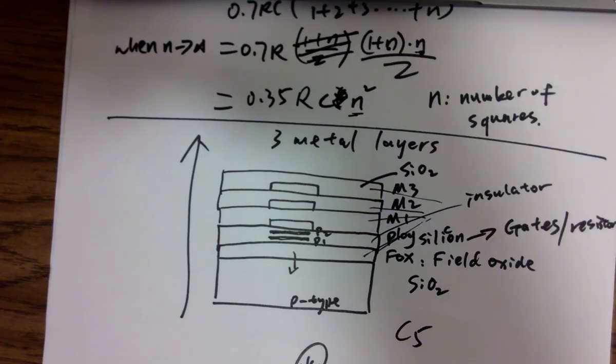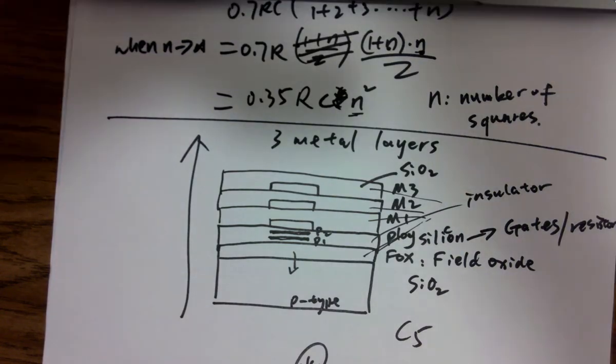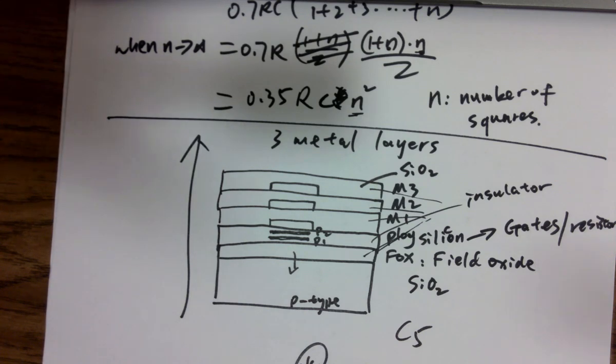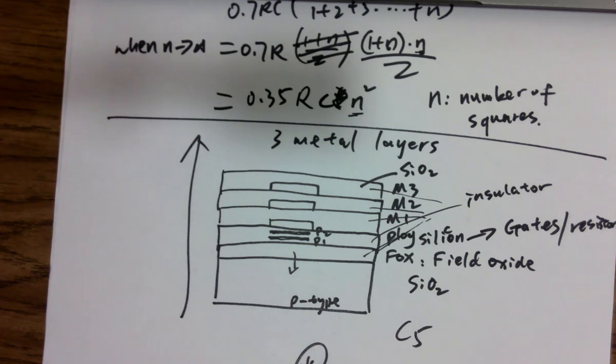and then come up. So you can imagine if you have like 40 layers of the PCB, you can highly integrate all the components in a smaller area. That's the motherboard of the desktop. It's probably like 20-something layers of PCBs, I don't know. So all the undergraduates are still making two-layer PCBs, which is fine. I mean, the tools do all the drilling. You are manually drilling the holes, so it's okay.